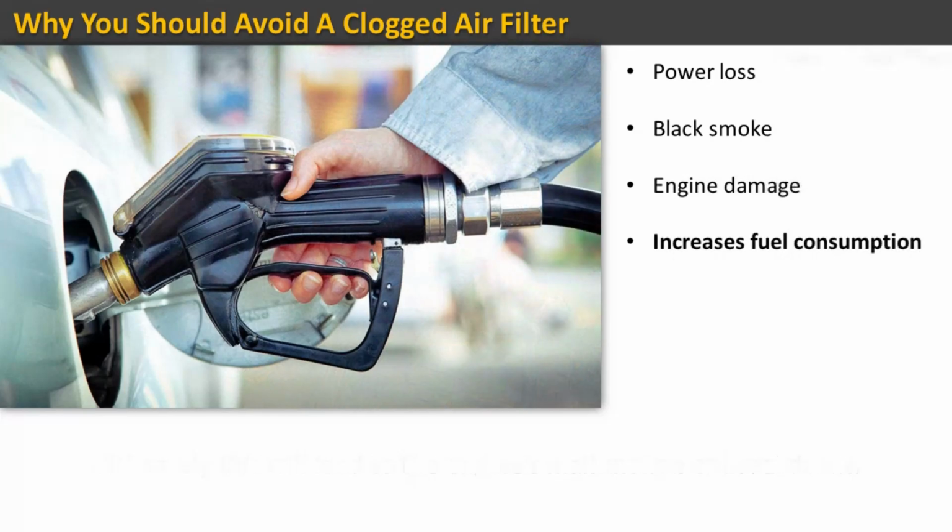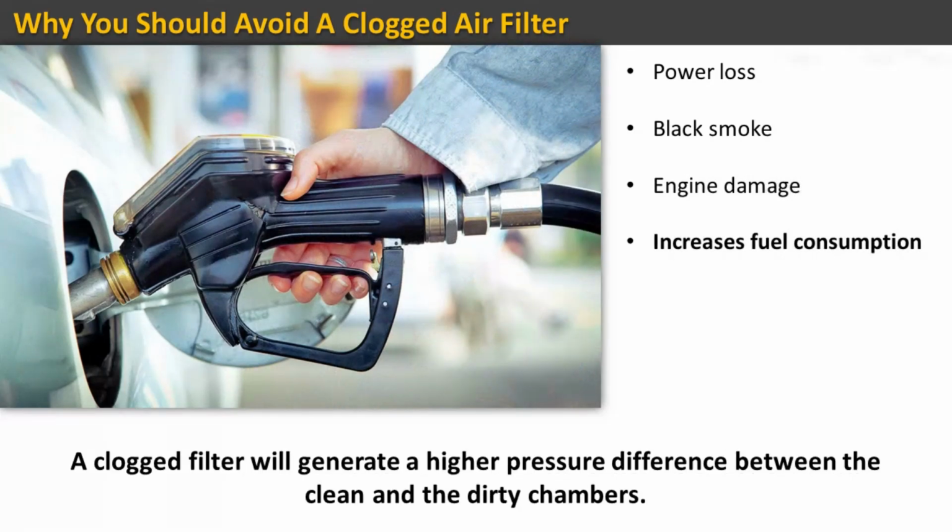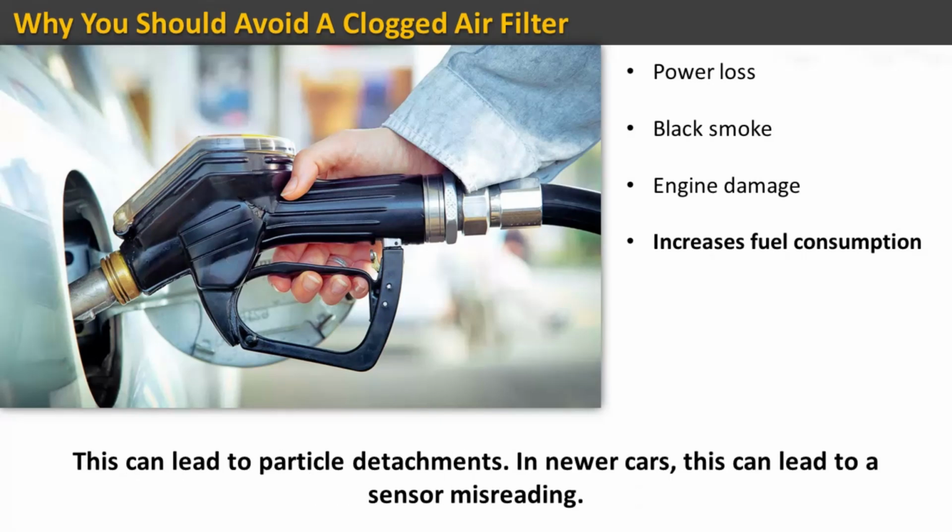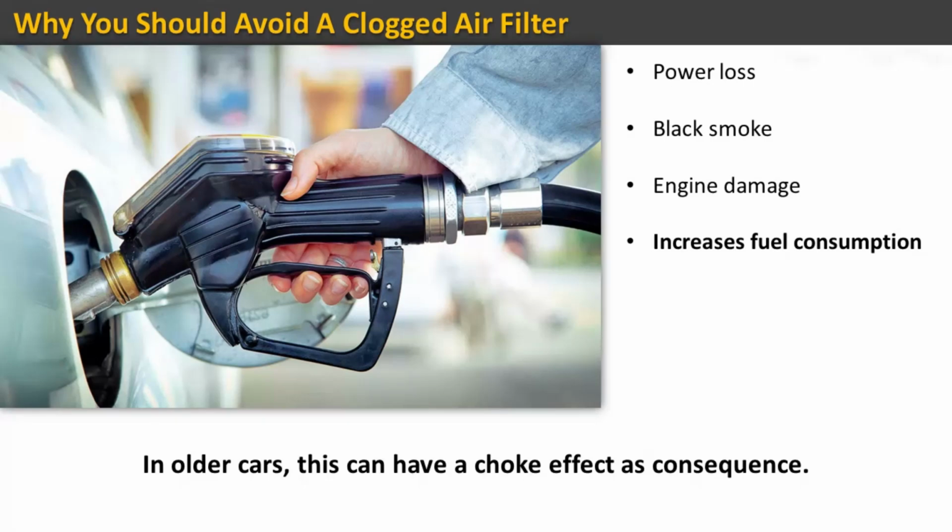Increases fuel consumption. A clogged filter will generate a higher pressure difference between the clean and the dirty chambers. This can lead to particle detachments. In newer cars, this can lead to a sensor misreading. In older cars, this can have a choke effect as a consequence.